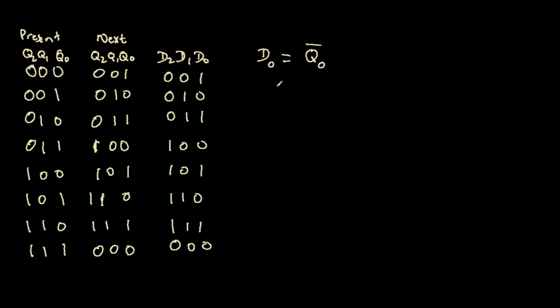That is perfectly fine. For our next significant bit, D1, that is a little more tricky to analyze without using a K-map. However, if you take a look at it, notice you have 0 in the first column, then you have 1, 1, and then you have a 0. Every time we have a 1 here, it occurs when your Q2 is 0, and the next set of times we get 1s in D1 is when your Q2 is 1. So the value of Q2 does not determine your D1. So we should look at Q1 and Q0.